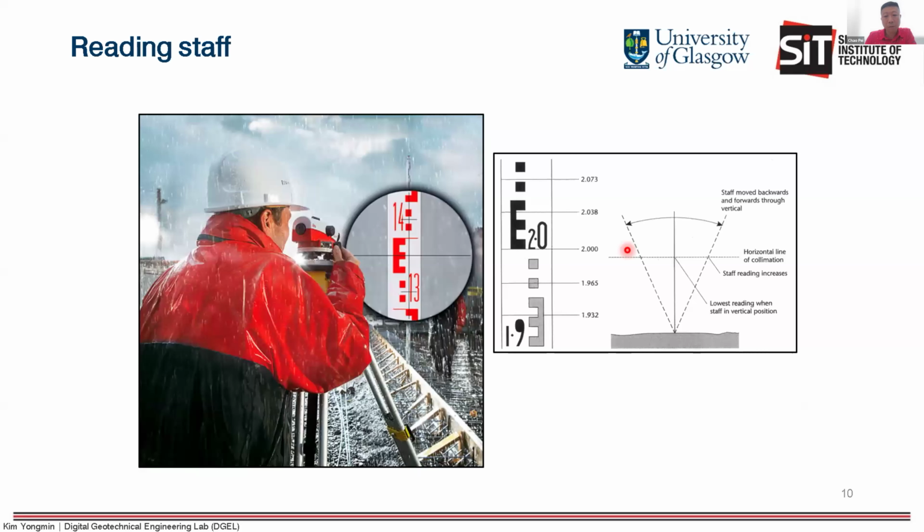Okay, reading staff. This one we already covered during the lecture. Remember, the staff must be vertical. Don't tilt it front or back or left to right. It will all affect the readings.